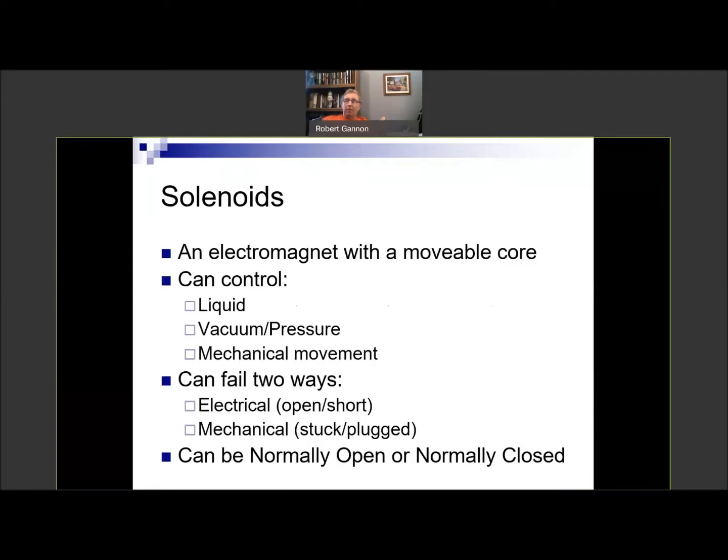We see this kind of a lot with things like EVAP vent solenoids. You hear them click, but when you're smoking the car, they click. They're supposed to be sealed, and you still see smoke leaking out because they have a tendency. They're down under the car. Rust gets in there, corrosion. They won't seal up anymore, and the seat becomes dirty, so it doesn't seat well.